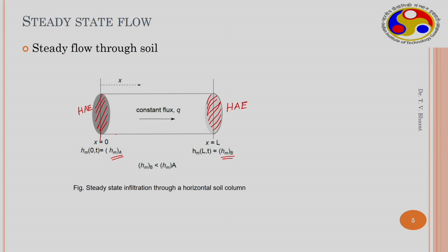Then you allow the water to flow under a certain head, and also you give air pressure UA and water pressure UW. So the water pressure difference, delta UW, can be maintained across this soil sample, but then a constant UA can be given. So therefore UA minus UW is maintained at these two boundaries. This value may be different.